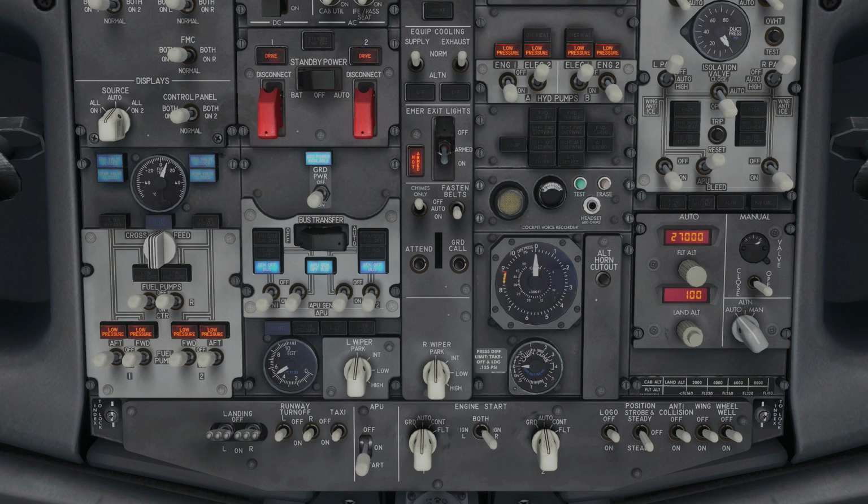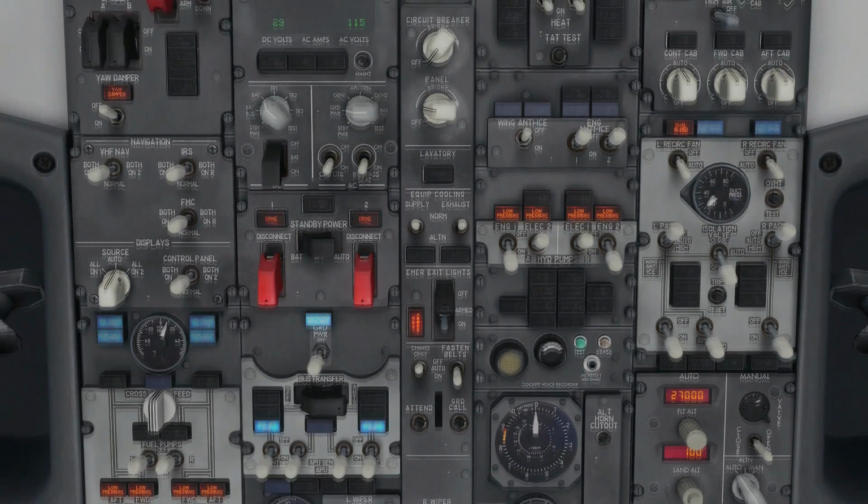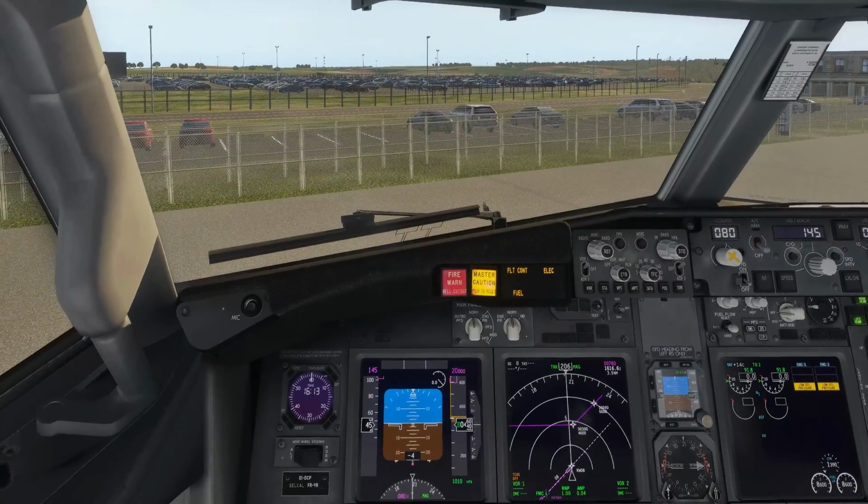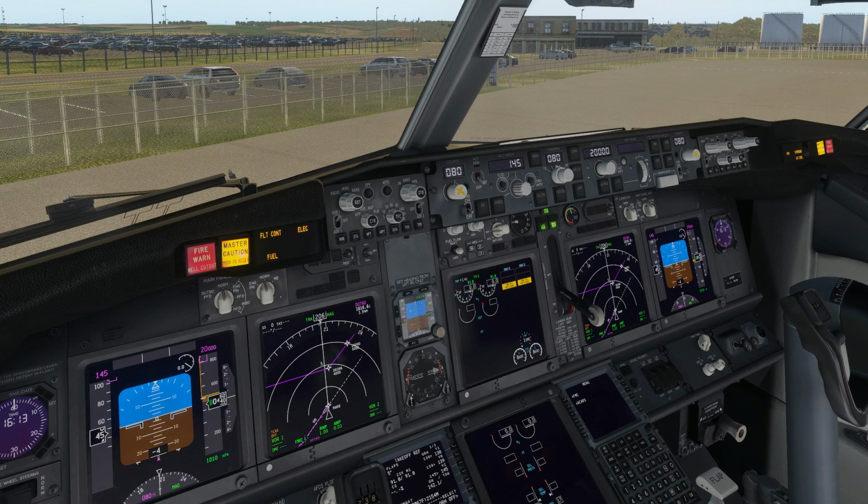Okay, so now it's available, we want to turn them on. After that, APU and engine bleeds are on. Our AC and DCs now go to BAT and APU gen. Now that's our preliminary pre-flight procedure. Now we do our pre-flight procedure, which will now be as follows.